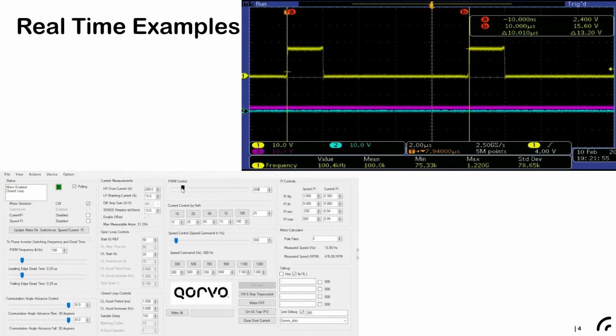So when I change this value here, I am changing an internal variable called duty cycle that is fed into the CCR for this PWM output. Okay, and that is happening, obviously, in real time, and the firmware is updating the CCR register, and then the hardware takes over, and every single PWM cycle is basically generated with that duty cycle.